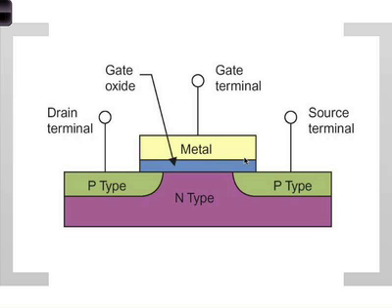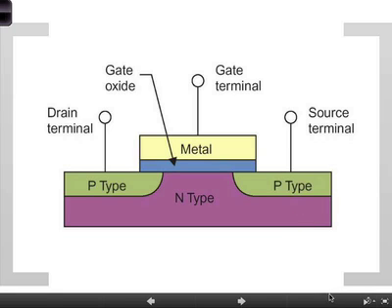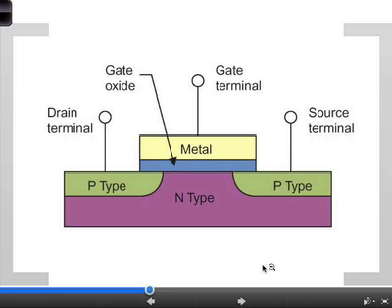Typically, remember, the source is usually connected to the body, which is this substrate, and grounded. Okay? These two things are usually connected together, the source and the body, and they're grounded. The body is typically just the silicon wafer, the wafer that's fabricated on. And that's the ground terminal, typically. The whole thing is grounded. Okay? And that in your digital logic, your ground line, that's basically it.